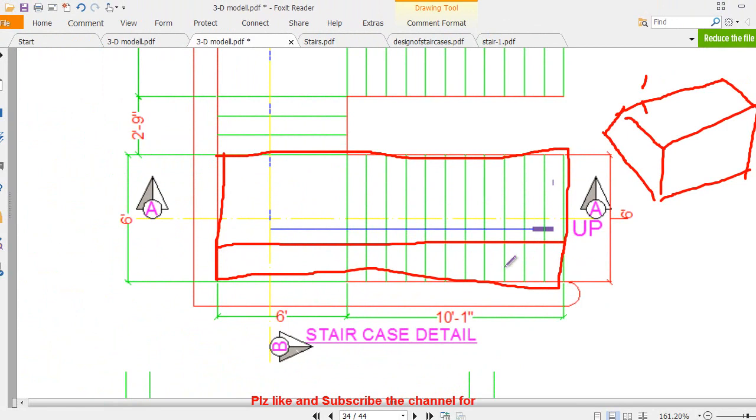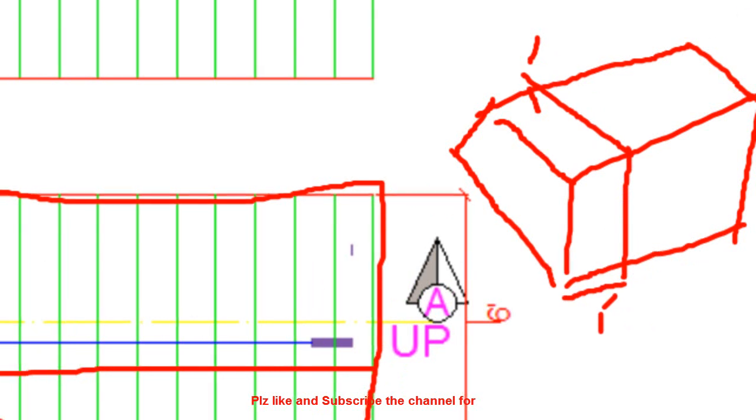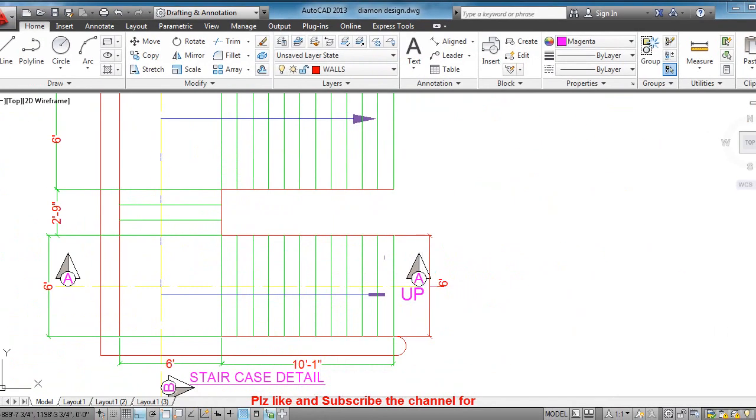Here you choose a one-way slab design, and in that case you just need to consider a 1 feet strip. So you have two options, and I suppose that I am doing the calculation as a beam. Clear?